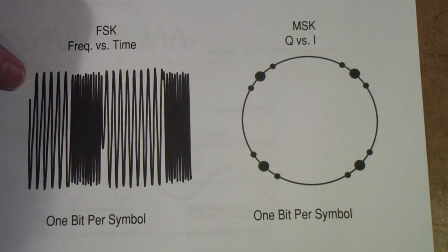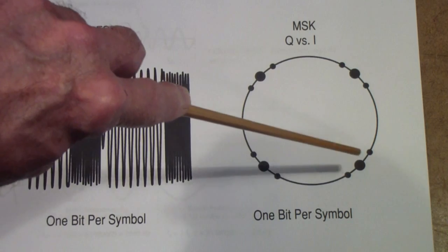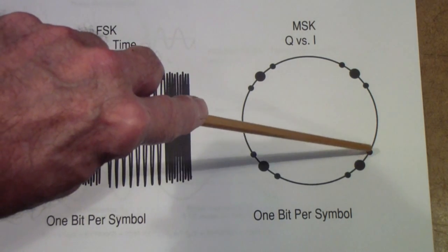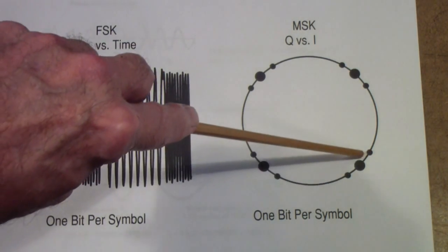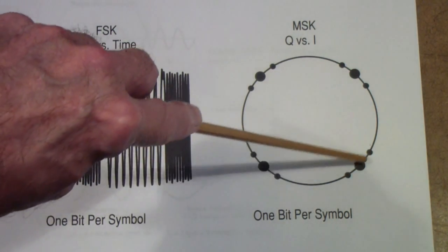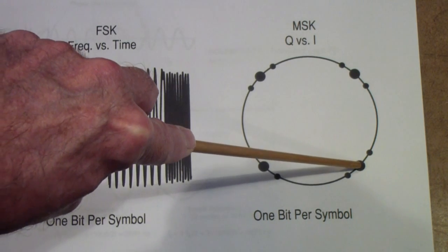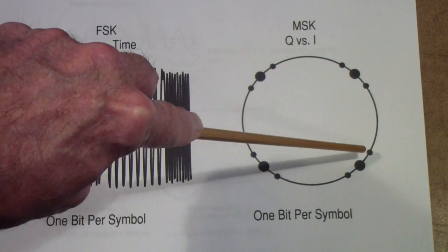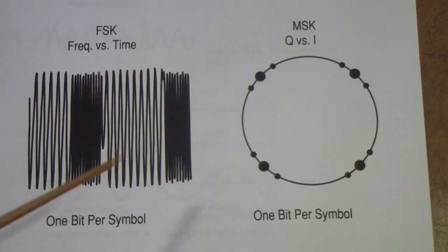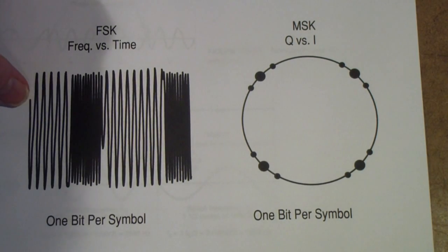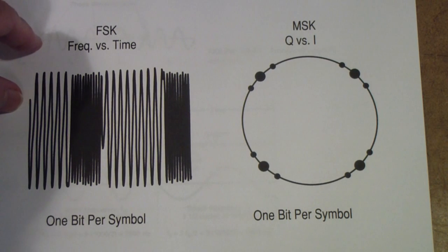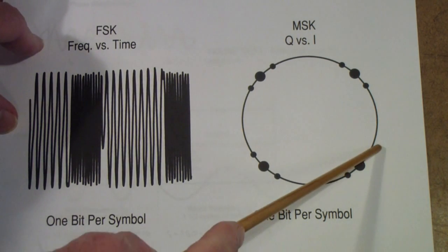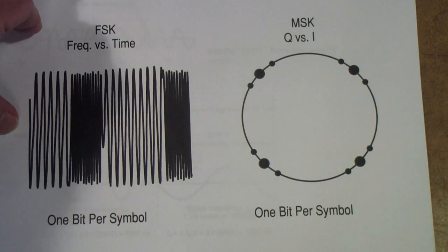In other words, a zero crossing interval. What that tends to do in the constellation diagram is to actually group a series of symbols around the symbol rate here, so that, as you'll see when we display this on the scope and on the spectrum analyzer, there will be a grouping of symbols.